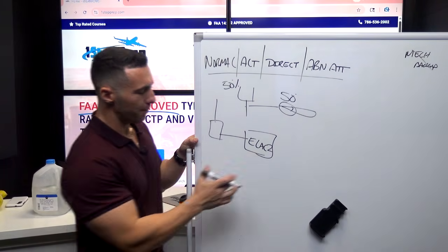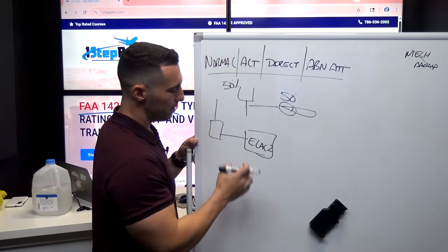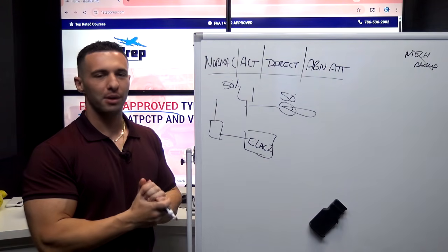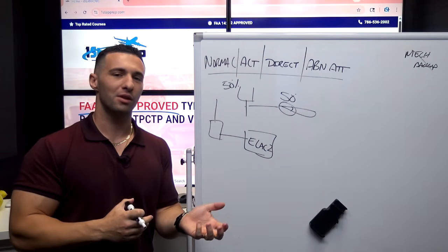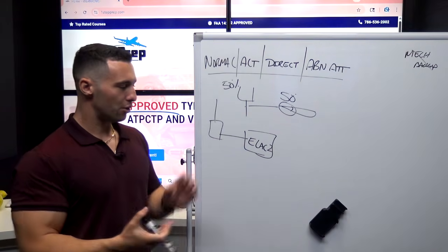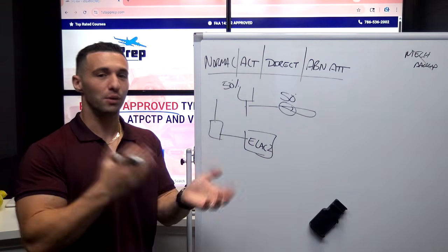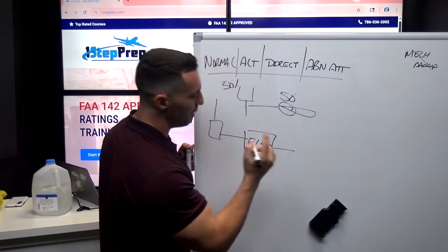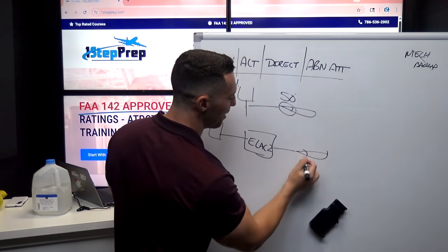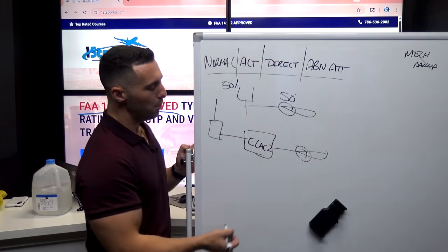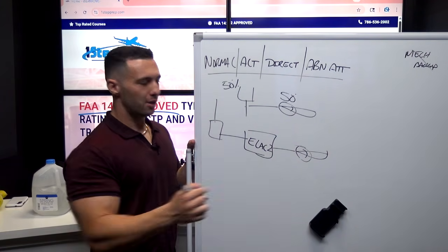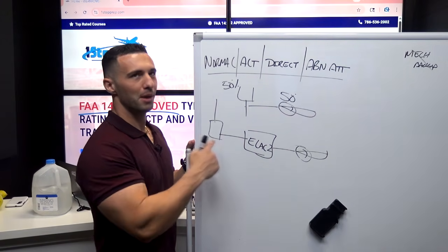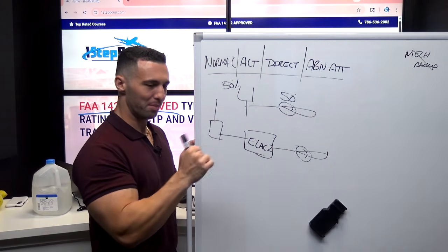So the side stick here, when I pull the side stick, or I push it or I roll with it or I do whatever I do, I'm actually sending a command to an elevator aileron computer, and namely ELAC2, because ELAC2 is the primary driver of the elevator. That's somewhat relevant and important because ELAC1 can also provide pitch control via the elevator, but it only has authority through the blue hydraulic system to run the elevator, contrary to ELAC2, which has green and yellow authority on the elevator.